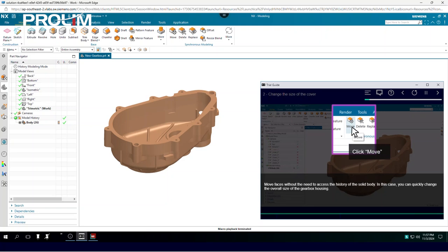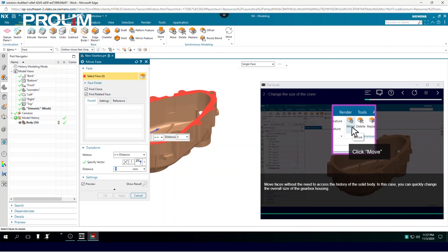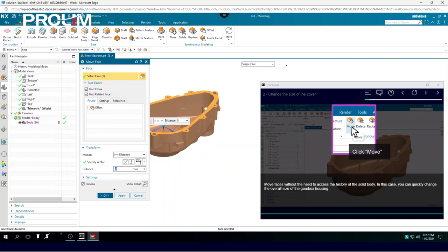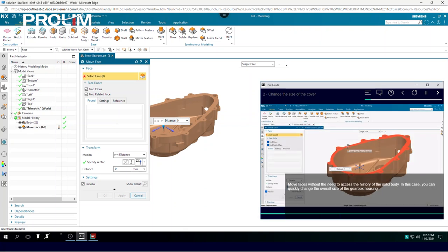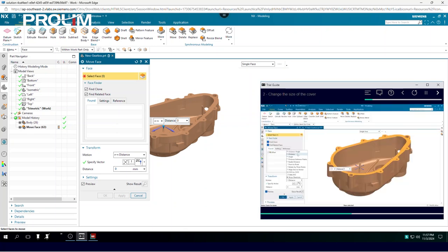First things first, as I have done this, I'll be doing it pretty fast. You can do it slowly, reading these scenarios and these prompts, like what it is doing and how, and you can go through all of these exercises one by one. So I'll be moving this handle here. For example, I want to move this handle by a certain distance, like say 10 mm. I'll say in the Z direction here, I'll say apply to this, right? So when we see the prompts here, you can see select the face, move this handle. You can see the same steps will be followed.